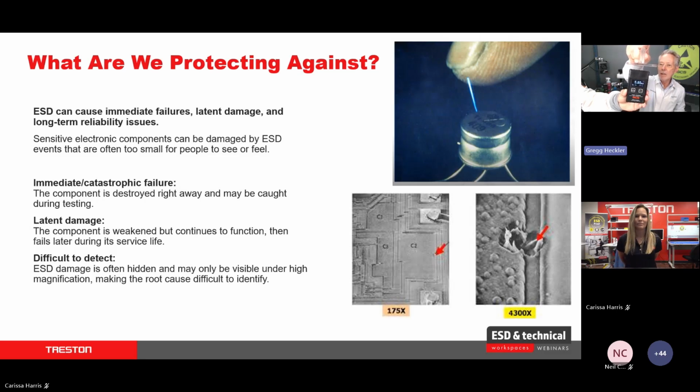Mm-hmm. What I got there? 5,000, 6,000 volts. 5,000 volts. But now I bring that isolated conductor in there. What I have is about 3,000 volts. So you can see obviously that the insulators charge up greater. However, you'll see that this one's positive, and you may see a minus sign there on the left. This one is negative. Each one of these is a static charge of a different polarity, and each of those polarities can cause damage.